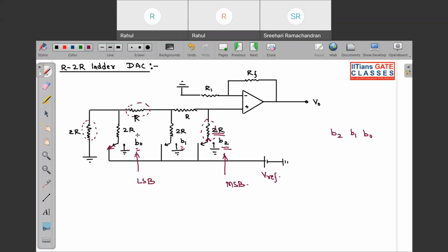Now this circuit, depending on the input, you can solve for your output. Okay, you can solve for output. So this will be a simple combination of analog circuit and your network theory. Okay, so you can solve it. You need to apply the concept of virtual ground. And as this is so, whatever is the input over here, you will get over here. So if that is Vi, assume you are getting your voltage Vi over here after solving, this is your non-inverting type of R2R ladder.